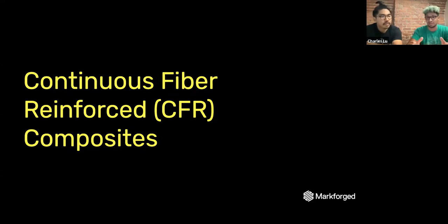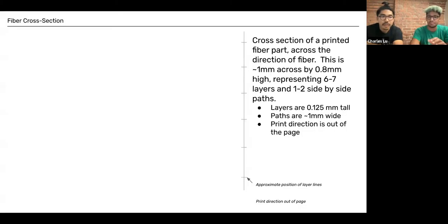On our industrial series, you're able to print 50 microns with the highest grade quality, where you get, as we like to say, an injection molded type finish on the surface. You also get repeatability because we've designed our own material and tuned our printers to it. So it's both an aesthetic component to why our Onyx material is superior, as well as not compromising any of the strength that comes inherent with having chopped carbon fiber within the nylon.